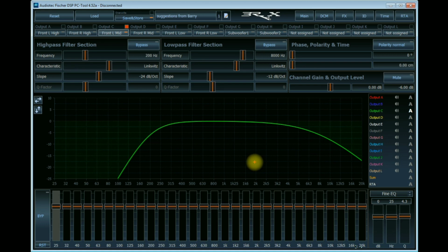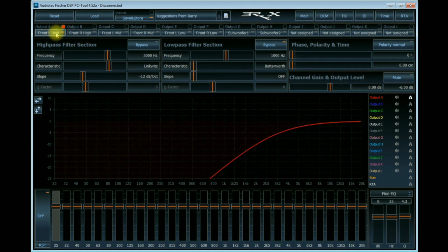Now, there is going to be a low pass happening at a lower frequency using crossovers built into the amplifiers. And so, just to state this a different way for clarification, this is what I mean about using a combination of DSP filters and amplifier filters to build the bandpass. I can't show this to you all in one picture here, but that's what the overall end result is going to be for the mid-range.